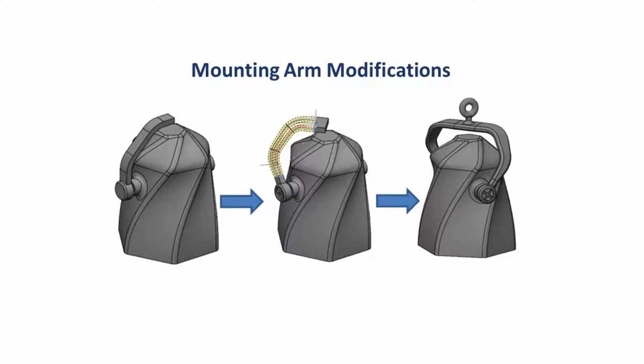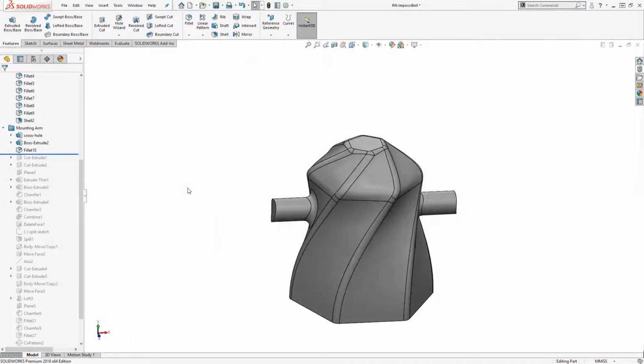So where I'm going with this is sometimes instead of just deleting features and starting over, there's ways you can leave that design history in there. The minor downside is that it might affect rebuild times and file size just a little bit. So if you're interested in the most optimized possible model, yes, you would want to clean out those unused features, but here it allows me to show you what I was thinking as I built this.